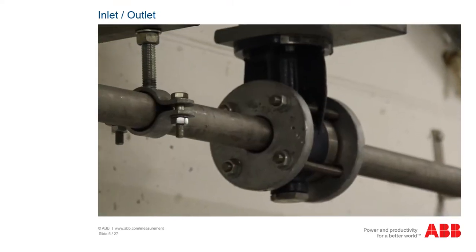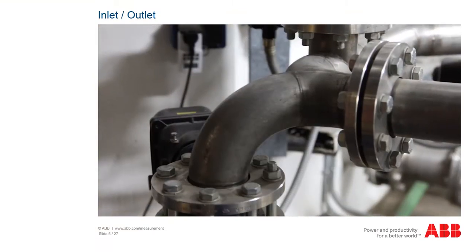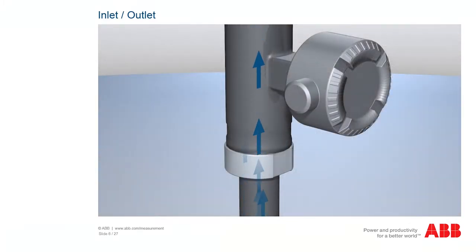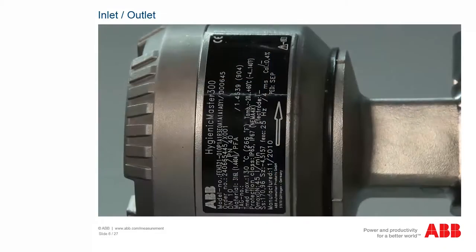Gates, controllers, and other obstacles can also negatively influence the flow profile of the medium as a result of turbulence. Therefore, it is important that after an elbow or any other obstacle, the medium can homogenize sufficiently. To allow this, a straight area must be reserved on the measuring unit in accordance with the specifications or the data sheet, with at least 5 or 10 times the nominal diameter of the flow meter in the inlet area and at least 2 or 3 times the nominal diameter in the outlet area. The nominal diameter, dN, of the flow meter is noted on the nameplate. For the factor table, see the data sheet.